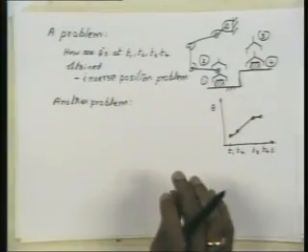By doing simulation. What do you mean by that? So basically we have to check for every point of time from T1 to T4, for the corresponding thetas, what are the positions of all the links, and whether the material parts of those links are colliding with either each other or any part of the environment, right? We need to check. What you mentioned would be corrections if we find that there is a collision. We need to then correct this particular trajectory which we have got and take care of that, right? That is actually a higher level problem. We are now looking only at that.